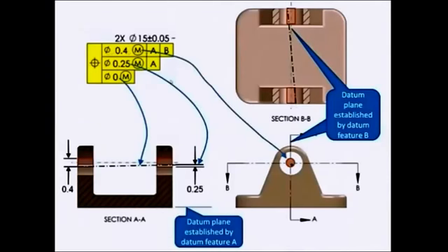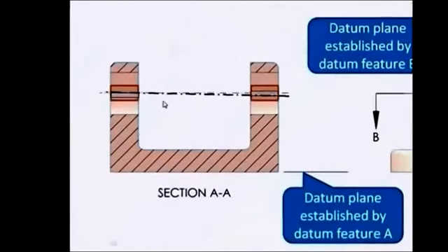So you'll see that this 0.4 is a cylindrical zone, shown over here in this view, and here's a side view of the cylindrical tolerance zones. And that limits where this axis can be with respect to the datums, or the origins, on this part. So if I animate this, I think you can see it a little bit better. The axes cannot go outside of the 0.4, and because of the second segment that we've added, the axes cannot tip more than 0.25 with respect to that plane established by our primary datum feature A.